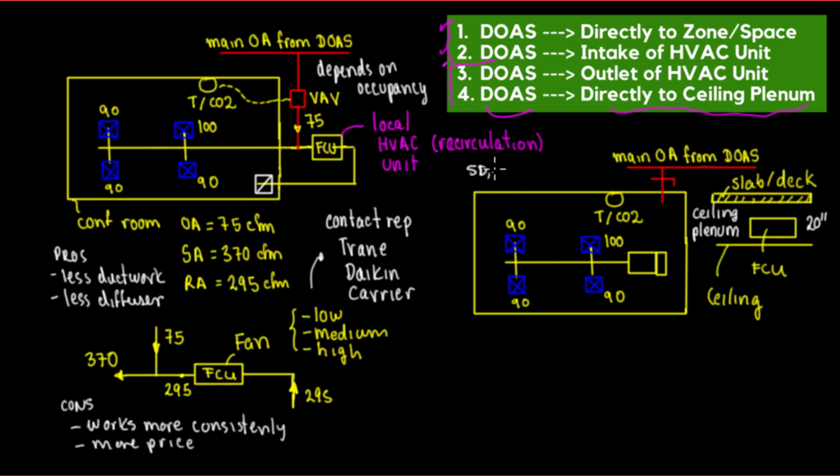SD, DD, and then CD. So it's very important to coordinate at SD level, like a schematic design, because then you are going to avoid a lot of work done in the DD design. So SD is very, very important to coordinate. It's better to get much space, honestly, because then you're going to have the interaction or the clashes with the plumbing, piping, fire protection, electrical events, so it gets crowded in here. So it's better to have more space. Give it a little bit more, right?